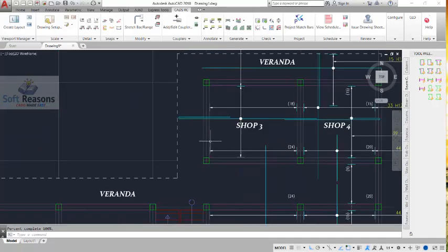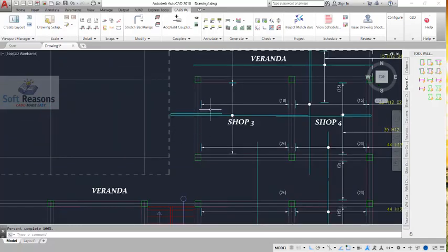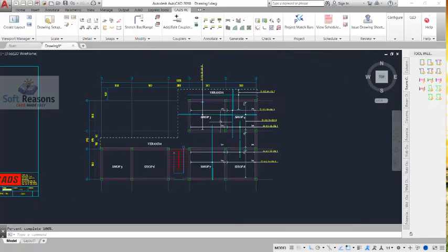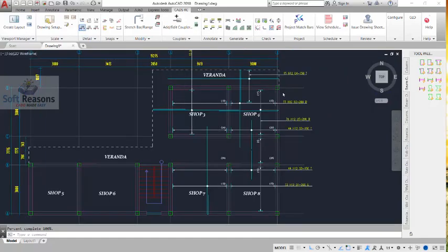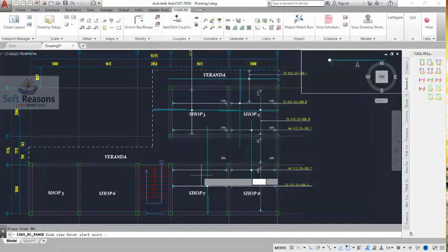So we proceed. We need to have a top bar right here, so that we hold down these returns successfully. For us to do that, we will get back to these provisions, and it's going to be shape 0 this time around. This is going to be T, which is the top bar. See, the bar mark has changed automatically. Click on the OK options.